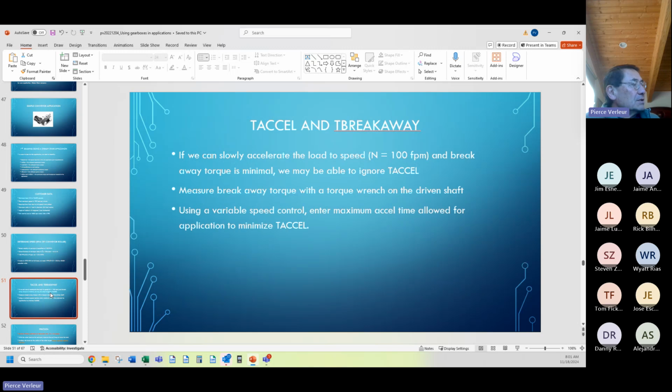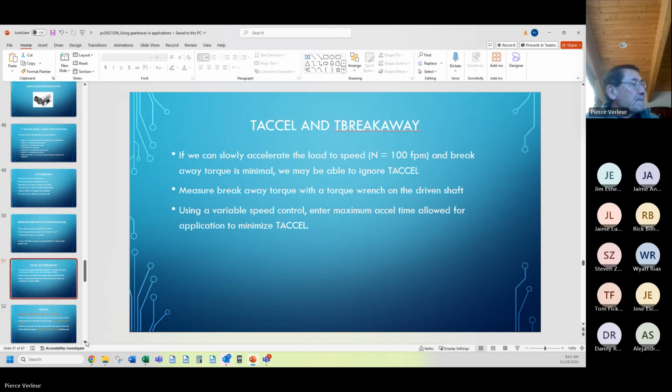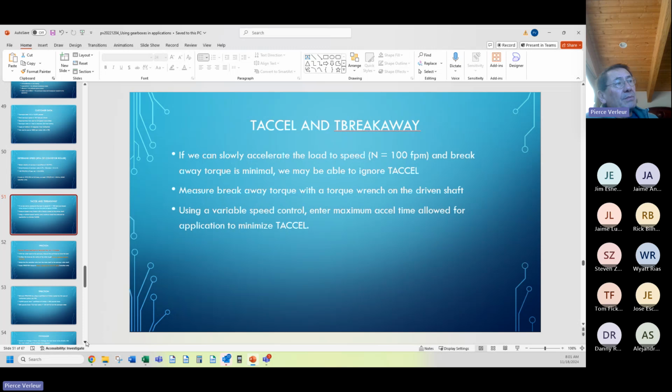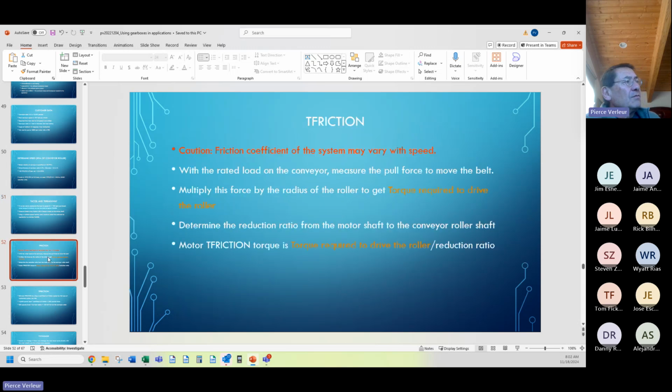Torque breakaway, torque axle, just talked about that. By the way, on worm gearing, it's really important because in addition to all the other static friction in the drivetrain, you've got higher static friction on a worm gear versus dynamic friction once the worm gear teeth start sliding on each other. Friction is always important in these applications. We make certain assumptions for bearings in terms of the gearbox and the sprockets, etc. But if you're dragging a load across sandpaper, we need to know that.